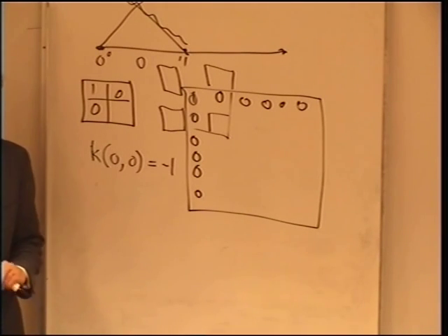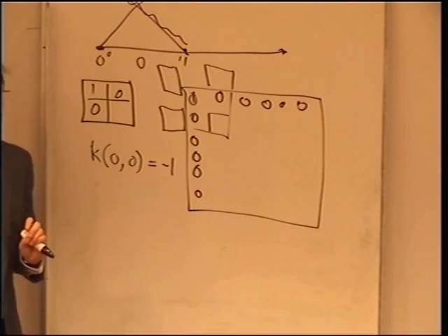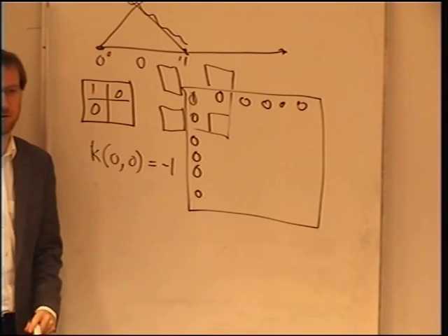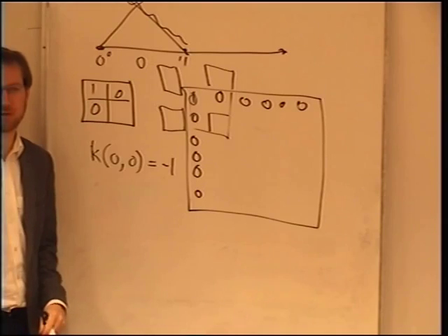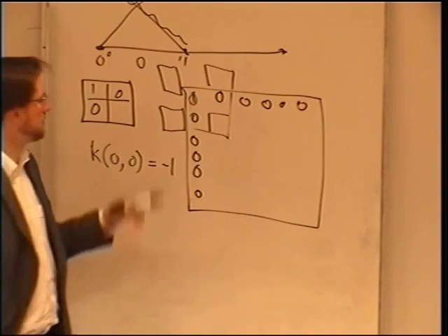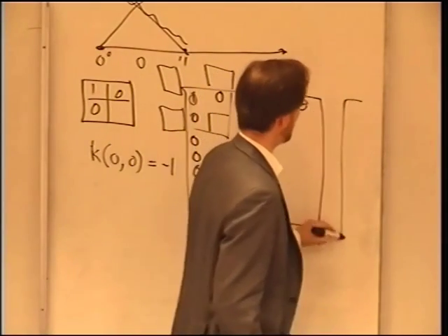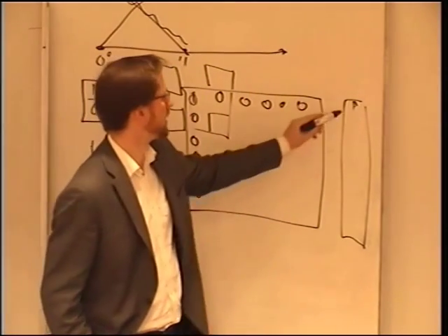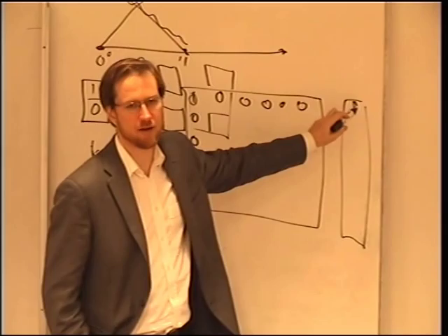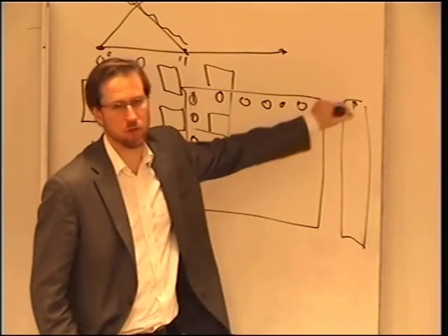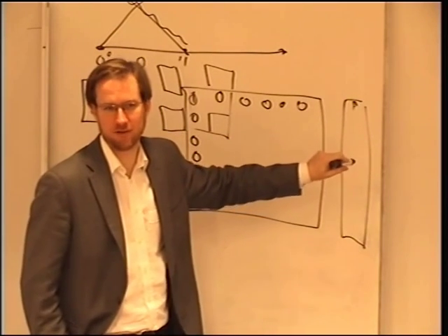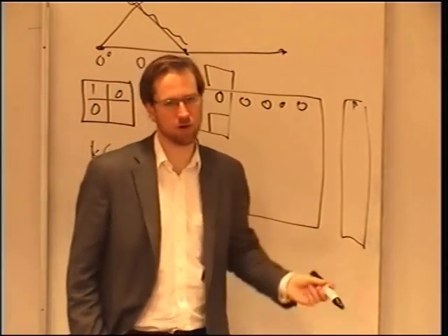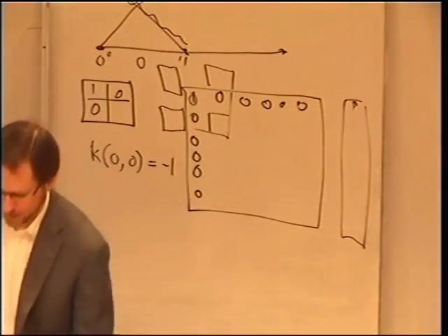On the right-hand side, we do something slightly different. On the right-hand side, we don't have this problem with needing to address the entries in the vertical. So we just tell the system to go right ahead and assemble the right-hand side as if there wasn't a boundary condition in there, and it puts the boundary values in there. And then afterwards, we go back and we clobber these values, and instead of having whatever the value of the integral is, we put the boundary condition value back in. And that's easy because this is just a vector, so it's very easy to insert into any point you like in that vector. So that's how that works.